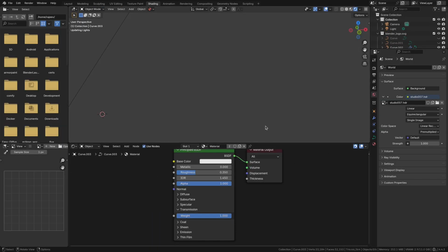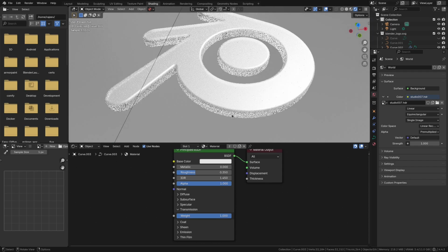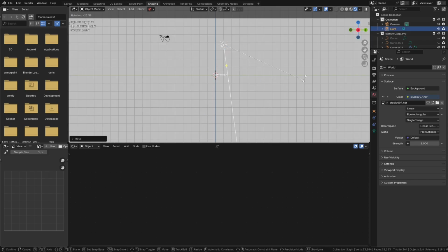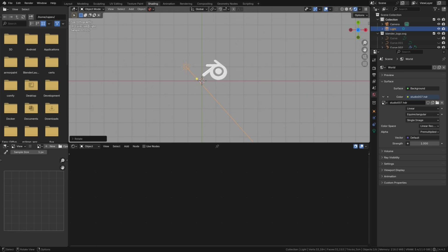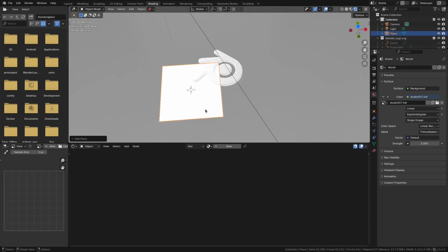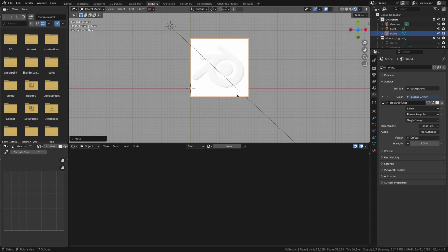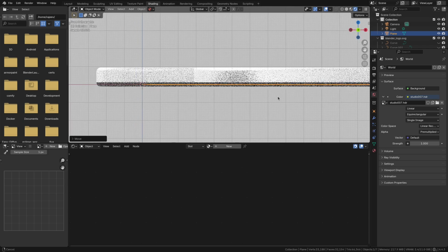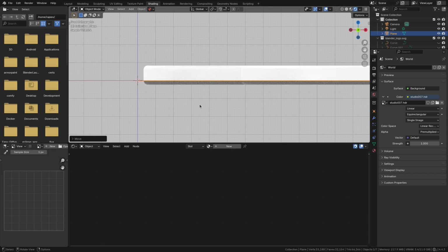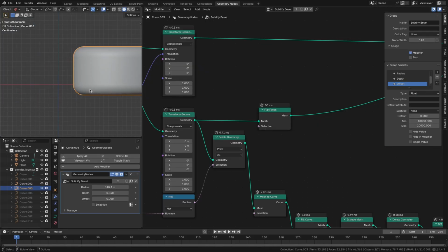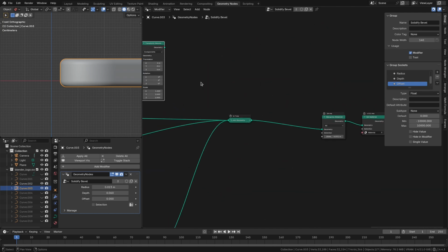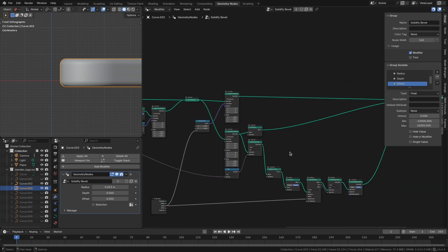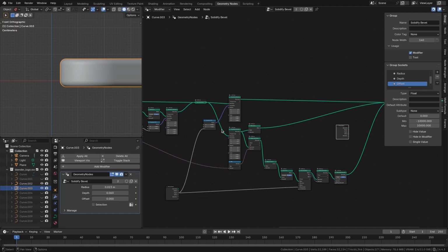Get back to the shading tab. Change the sunlight's direction. And add a ground plane to add some shadow and depth. The ground plane is created at a Z value of 0. The bottom part of the logo is below the plane. Translate the entire geometry by the radius value in the Z direction.